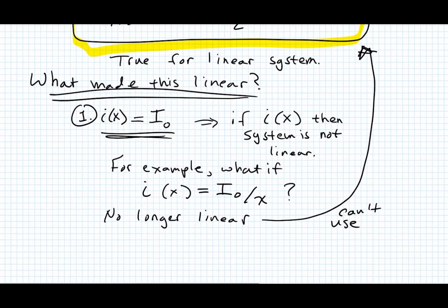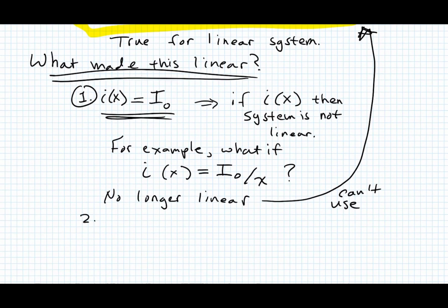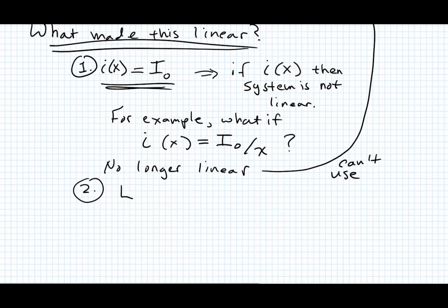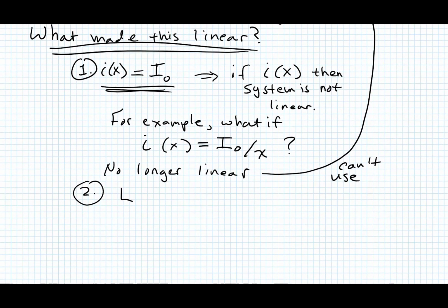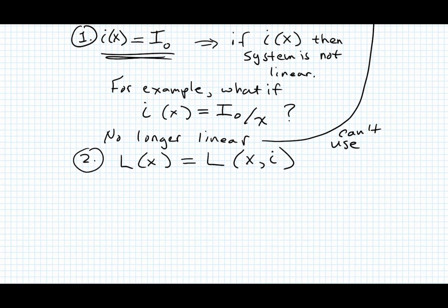Another one is, if L, which you already know, we've been through this with our chapter 2, L sub x, you have L, let me put it this way, L also changes with I. So if your L changes with I, an example of that would be saturation, right? Or a saturated core.